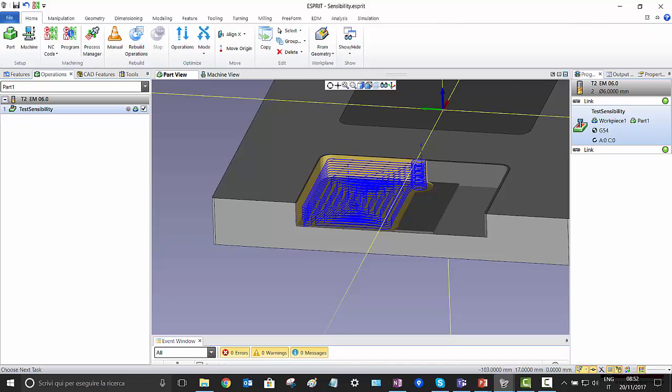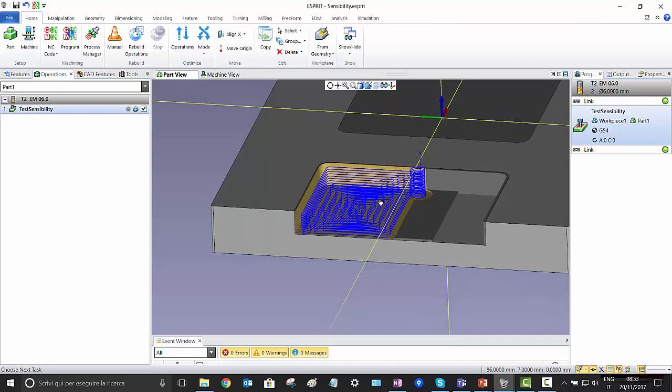And so the toolpaths got concentrated only in this left area. Why we have this toolpath here on the vertical wall of the left area? Well, this is absolutely correct, because if we machined immediately the bottom without previously having these passes above, we would surely have an overload of tool engagement, and so it would not be correct. So let's pass to the next improvement.